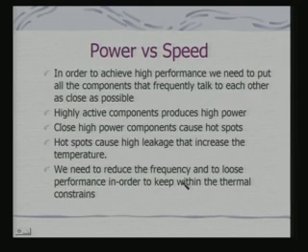So, there is obviously a trade-off in terms of power versus speed. In order to achieve high performance, we need to put all the components that frequently talk to each other as close as possible. Highly active components produce high power. Close high power components would cause hot spots.